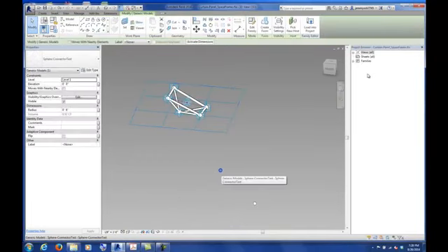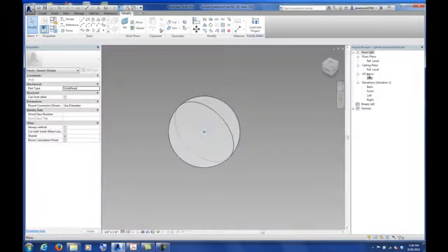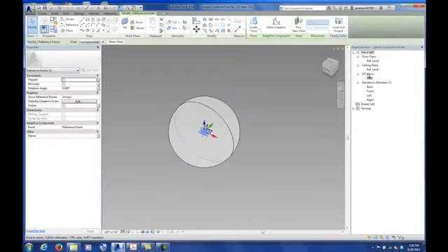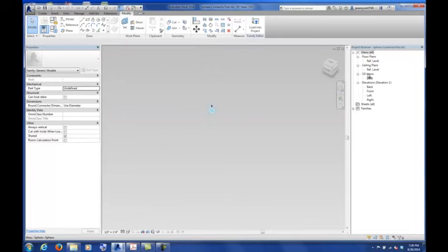There's one step that will fix that. If you go back into your sphere, click on that center point. You need to make sure that it's an adaptive point. So hit make adaptive. You'll notice an adaptive point because it'll say number 1 once you make it adaptive.